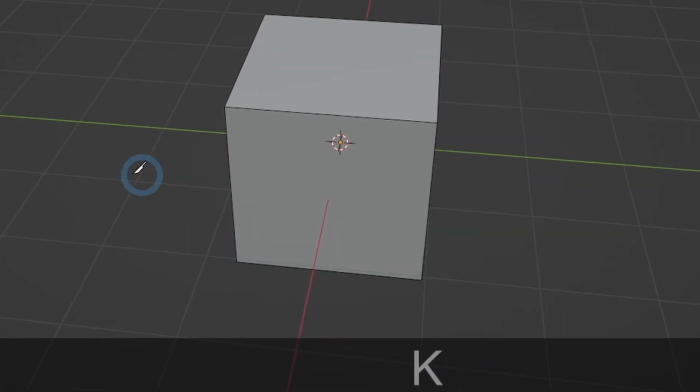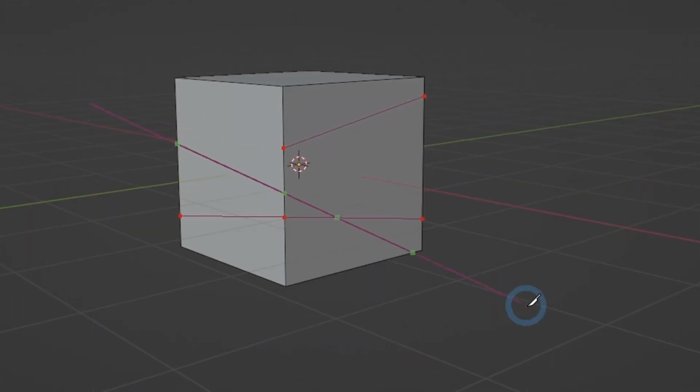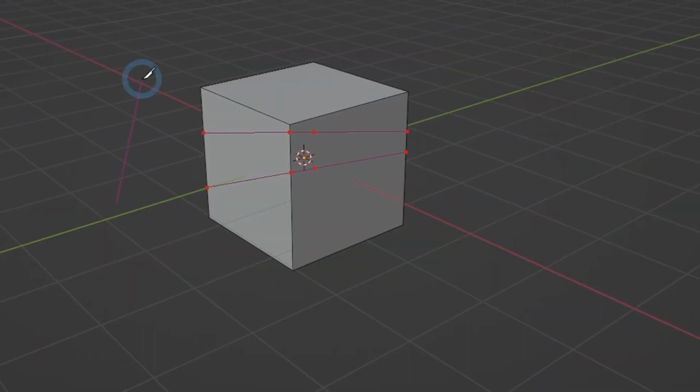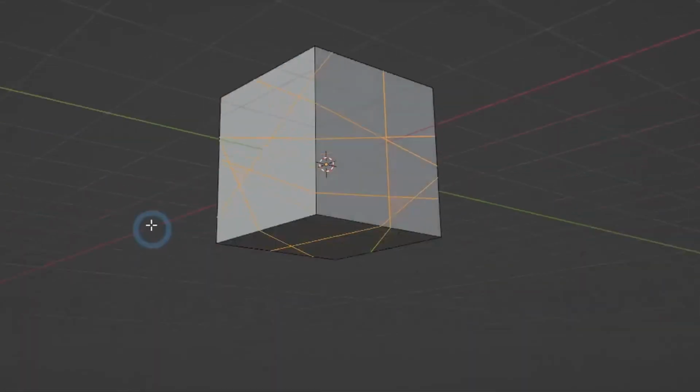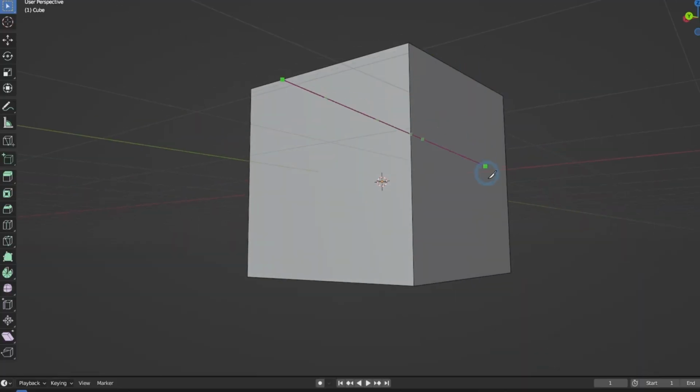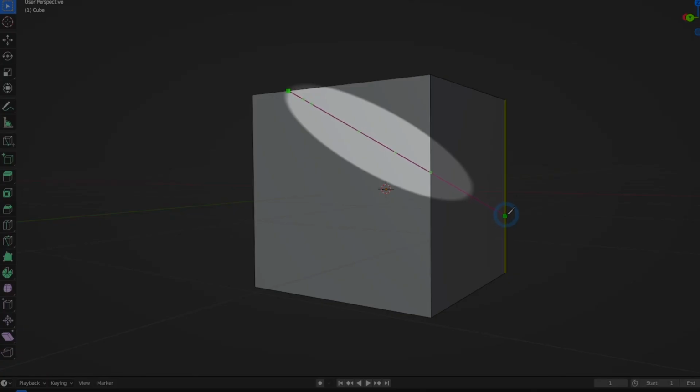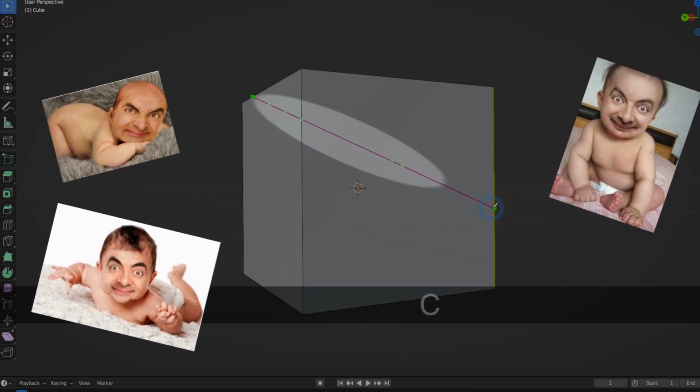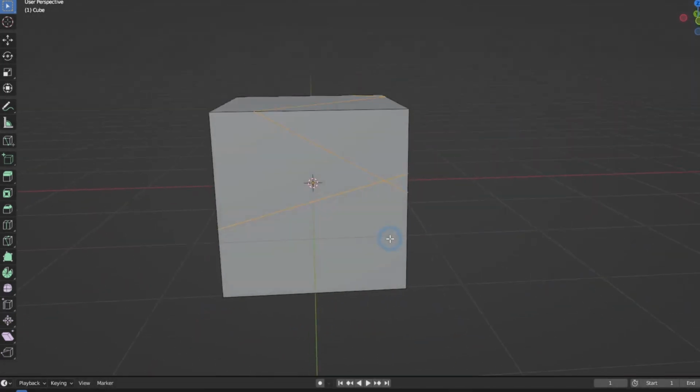The default mode of cutting with this tool only affects visible geometries, but if you press C, it's gonna turn on the cut through mode where it slices all the way through the model. And while you're doing this, you're gonna notice these little adorable vertex babies. Well, those are the vertices from behind the model where the slice is gonna cut through.